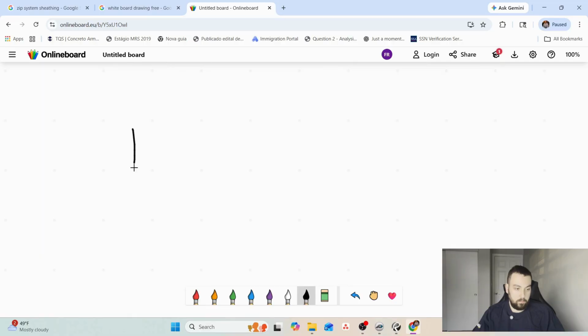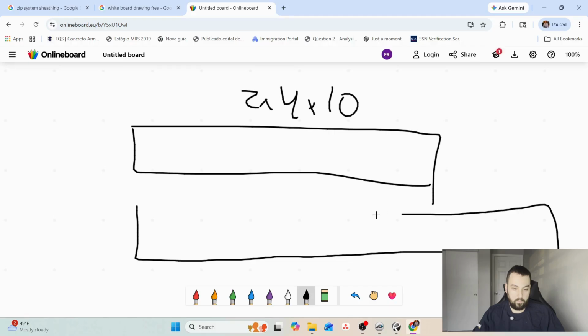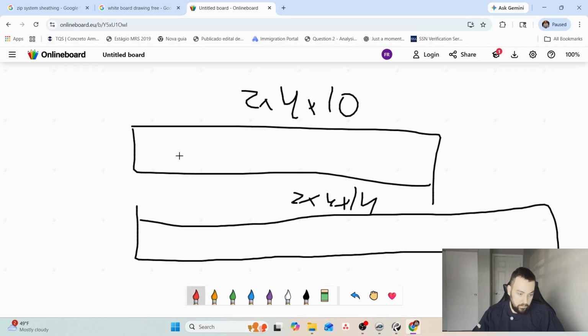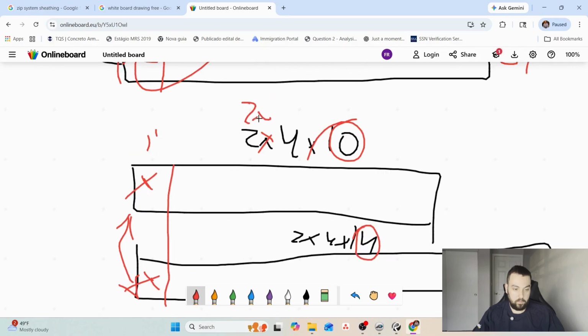But on the other hand, the 2x, so let's say a 2x4x10 and a 2x4x14. The price per linear footage is not the same. They are completely different. It can be double. It can be 50% difference. So we have to come up with the third dimension for estimating purposes, you know. And this is a good tip for you. If you're purchasing material 2x4x10, try and price the 2x4x12.